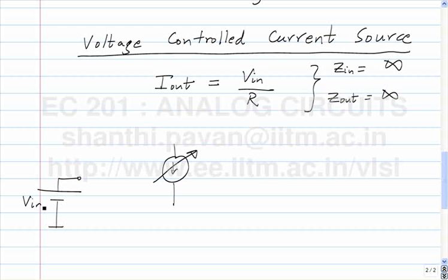What you will do is the following: you know that you have this gadget at the back of your mind, you know that you can compare voltages, because the MOSFET is a gadget that can produce a large current in response to the difference between 2 voltages. And when we say comparison, it means taking the difference.